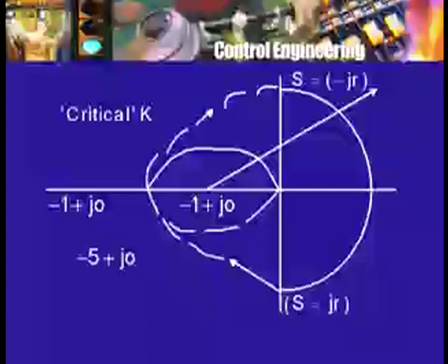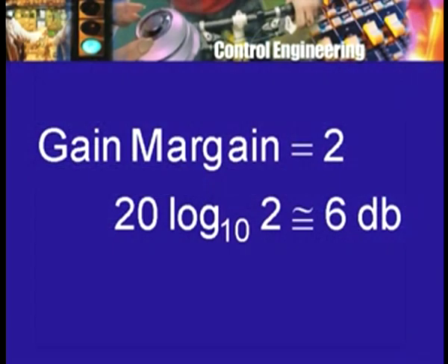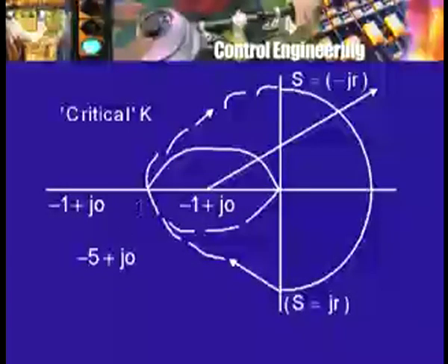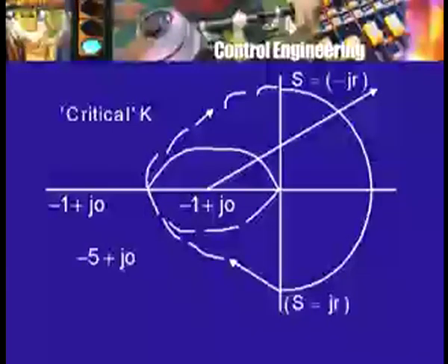And so, the gain margin in this case will be by a factor of 2, or you can convert that factor of 2 into decibel language, you can think of it as 20 log to the base 10 of 2, and that is therefore nearly equal to 6 decibels. So, one speaks about in this case that if for a particular value of k, this was the polar plot, this was the location of the point minus 1 plus j0, the point of intersection here was 0.5 plus j0, then in this particular situation the gain margin is of a factor of 2 or 6 dBs.